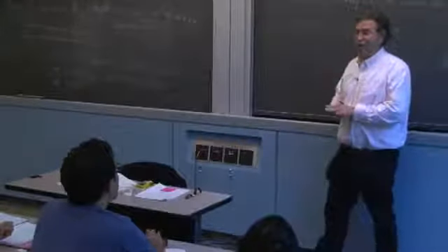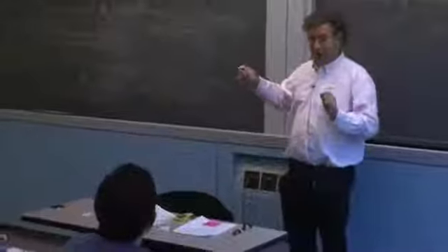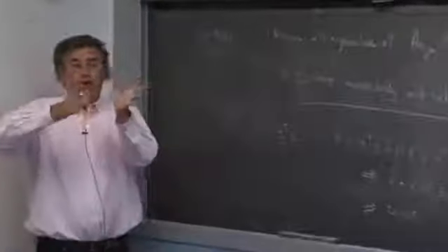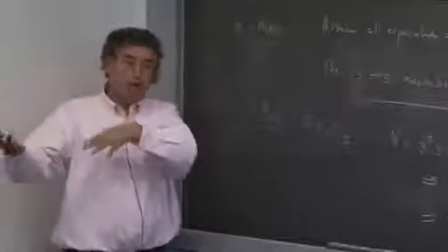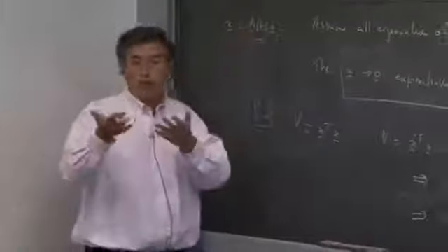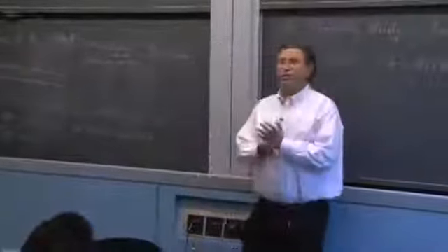Okay. So here we're proving the other way around, right? We're proving that if you have a system, and that could apply to a linear time invariant system too, whose eigenvalues of the symmetric part are all negative, then the system is stable. But it doesn't show the other way around, because the other way around we know that's not true. Good question. Any other question apart from this inequality I'll come back to?